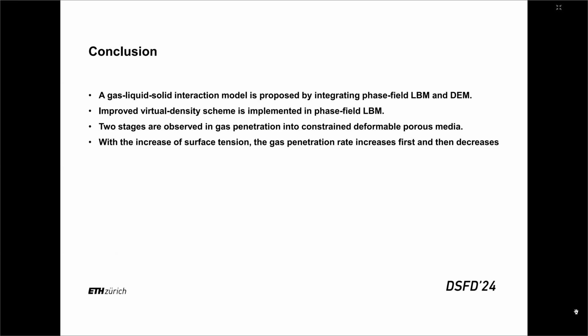And this is our conclusion. We successfully developed a gas-liquid-solid interaction model by integrating the phase field lattice Boltzmann method and discrete element method, and an improved virtual density scheme is implemented in the phase field lattice Boltzmann method. The two stages are observed in the gas penetration into the constrained deformable porous medium. And with the increase of surface tension, the gas penetration rate increases first and then decreases.